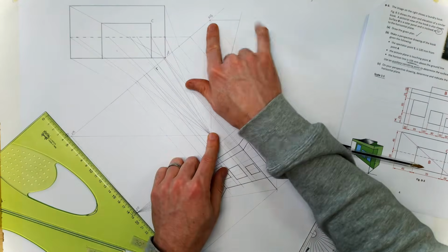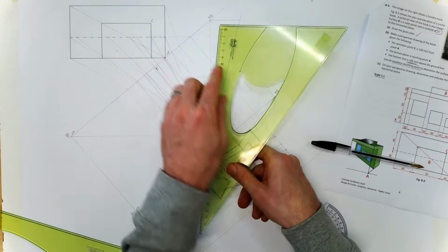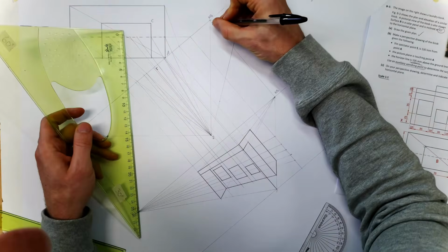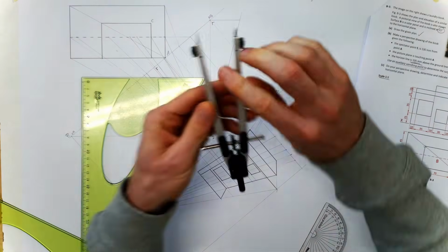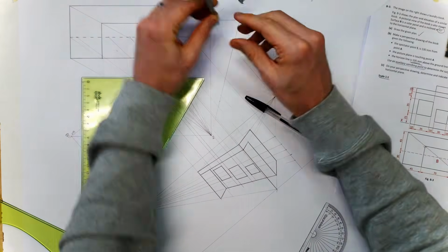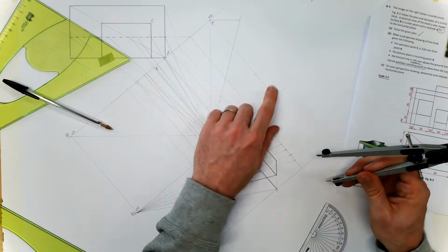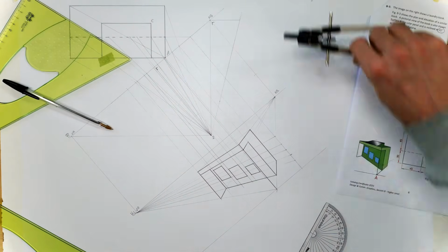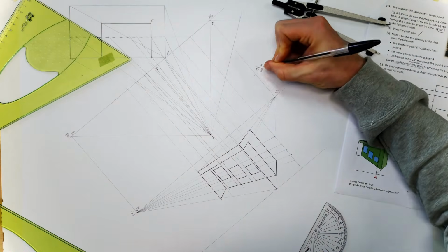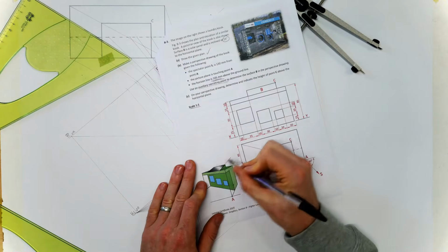It's a height above VP2. Remember that's what we're doing. We're folding it down, so it's a 90-degree triangle, and it's a height above VP2. Let's put in my 90-degree symbol. Let's get that height then, and we're going to step it off above VP2. We do not go across here to VP1. It's always on the VP2 side. So that's my auxiliary vanishing point. We're going to use that for these sloping surfaces.